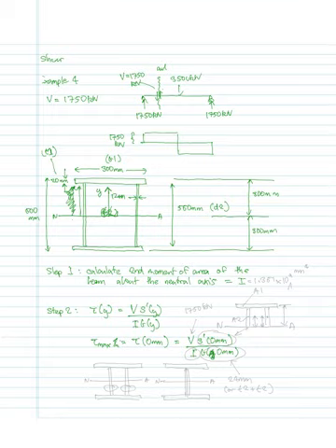So hopefully it should be obvious, if I drew a smaller to scale section with the webs here, that the value of I wouldn't change, and suppose I'd even decided to push the two webs together so that they're just touching, or there's only a small difference. The value of I is not going to change, and the values calculated are not going to change either.